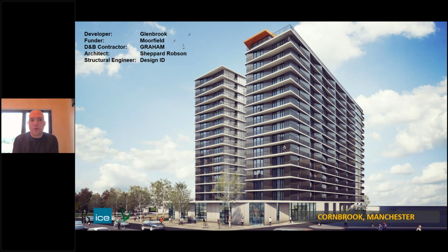So we worked very closely with Graham's. And we said, well, if we do some very detailed finite element analysis of each of these floor plates, and look at when the deflections will occur and what the deflections are likely to be, we think there could be some savings. So we worked very closely with Graham's and with their construction program. What we realized is that the floor plates themselves had been designed for a deflection limit.